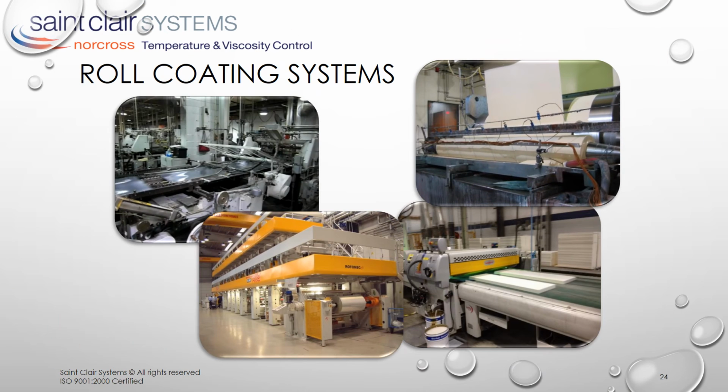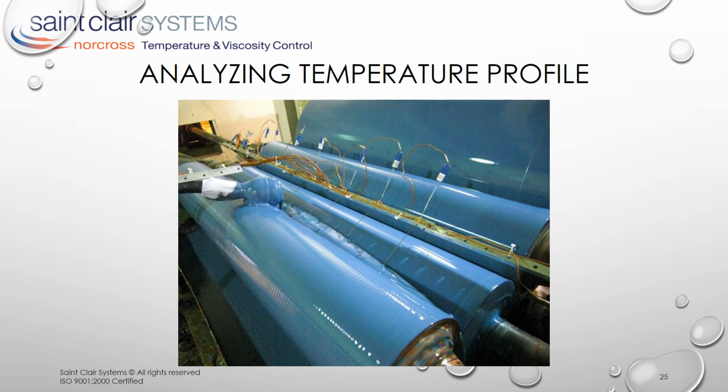There are also a host of different roll coating operations: pre-coated steel and aluminum strip, fabric and fiberglass web, juice box, corrugated and adhesive label stock, and can-making sheet, just to name a few. One of the fundamental differences between spray application processes and roll coating processes is that instead of being sprayed from a single point orifice, the coating is applied all along the width of the face of the applicator roll. Any variation of temperature, meaning viscosity, along this path will result in a variation in coating film build. In addition, friction between the rolls generates heat. Therefore, the mechanics of the coating system will endeavor to increase coating material temperature and thereby reduce its viscosity throughout the coating cycle.